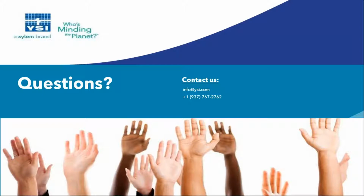Brandon, I've got a great question here from Jim, and I really appreciate these questions, guys, because they really reflect how deeply you're thinking about this. Jim asks whether calibration temperature should be similar to the expected temperature of the water you're going to monitor. In an ideal world, yes, it should, and you actually can do that, Jim. You could, for example, put those rhodamine solutions in a water bath that is similar to the temperature that you expect to be calibrating at, and then go through the same process that we just described.